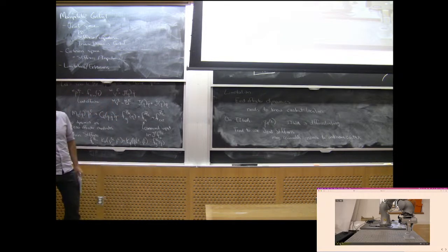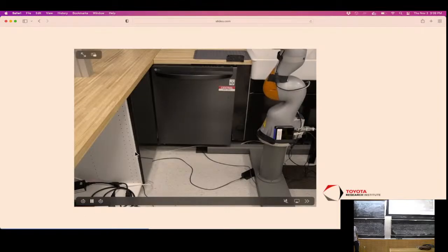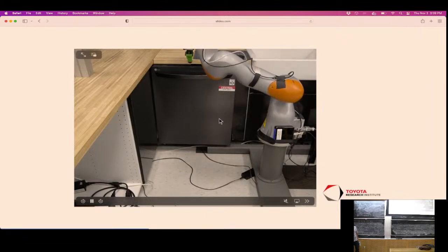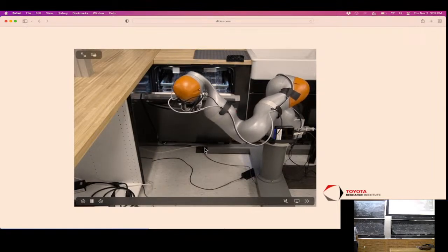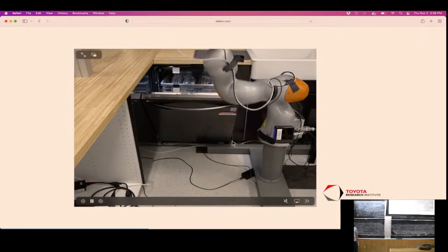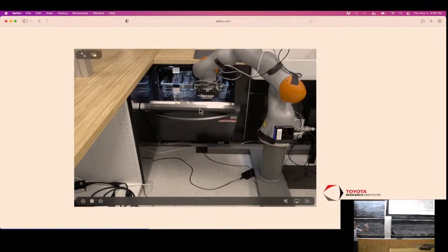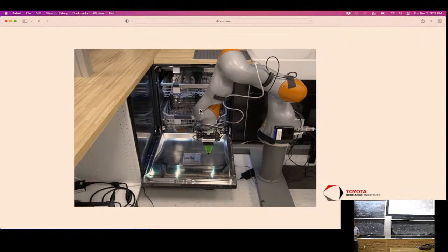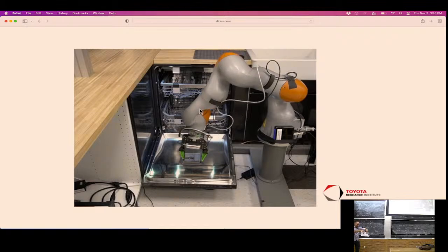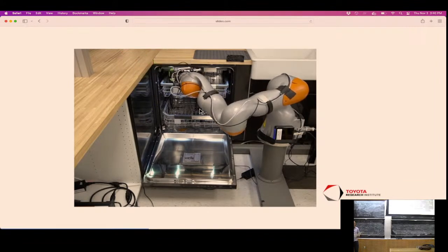And that's how we got compliant motion for things like opening up the dishwasher door. The trajectory of this was, I would say, carefully planned, but with a highly imperfect model of where the dishwasher door is, where the hinge on the dishwasher door was, and we are heavily relying on the ability for that robot, just like when I pushed it in joint space mode, to deviate from its planned trajectory in order to execute that task. If those gains were too high and the robot was pulling down on this and it was kinematically bad, the hand could get jammed and things would be bad. You'd blow a fuse. These things are pretty robust.